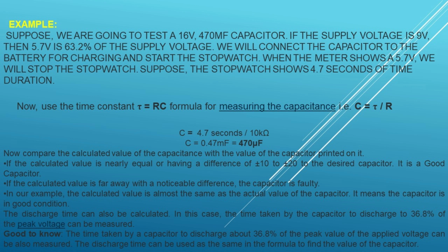Note the initial voltage reading in the voltmeter. If it is close to the supplied voltage you gave to the capacitor, the capacitor is in good condition. If it shows a far lower reading, the capacitor is dead.